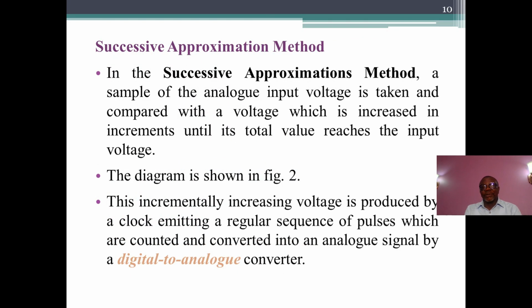In this successive approximation method, a sample of the analog input voltage is taken and compared with a voltage which is increased in increments until its total value reaches the input voltage.